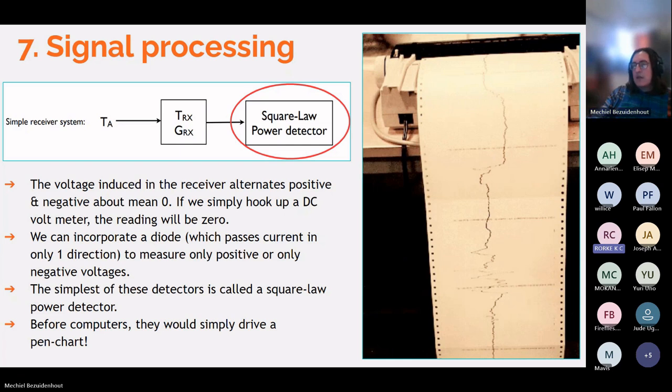So it's not like you tune the receiver. You actually want a width of signal. Yes, you measure a signal which is a superposition of a whole bunch of frequencies, but you limit it within a specific range using a band pass filter. So you say, I'm looking only at signals within this frequency range, and then using a Fourier transform, you decompose it into the individual frequency channels. Okay, thanks. No problem.